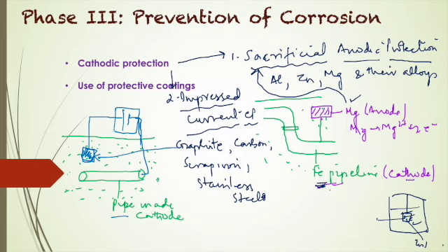Okay. So if we see the difference between the anodic and cathodic coating, anodic coating protects the metal from corrosion sacrificially, but cathodic coating protects the metal from corrosion due to its higher corrosion resistance, right? In anodic coating, base metal is not corroded even if it is exposed till all the coating gets consumed, whereas in the cathodic coating that is not the case, because even if small cracks or pores are present, it leads to the speed of corrosion of the metal surface.